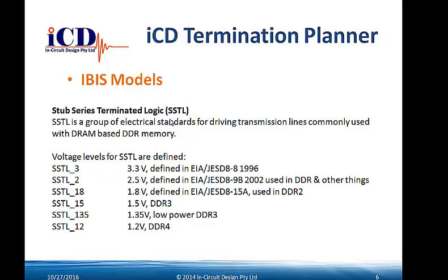SSTL_3 is actually 3.3 volt operation. SSTL_2 is a 2.5 volt, 1.8 is 1.8 volts, and so on. So we have all these different models which can be used for just your standard SDRAM or your DDR4, for instance, and also low power devices.